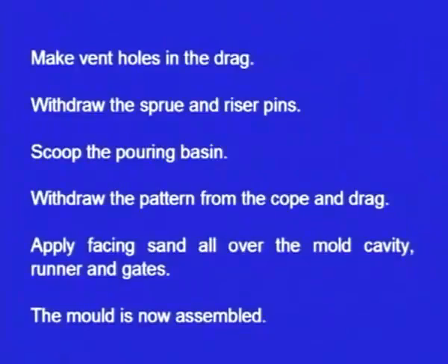Next we have to make the vent holes. Yes, sometimes the permeability of the molding sand may be poor. Permeability is the ability of the molding sand to allow the hot gases to pass through it. Yes, if the permeability of the molding sand is very good, no problem. Sometimes it can happen that the permeability of the molding sand will be poor. At such times we should be on the safe side. So we create the vent holes. As we have created the vent holes in the case of the drag box, in a similar way we have to create vent holes for this cope box also.